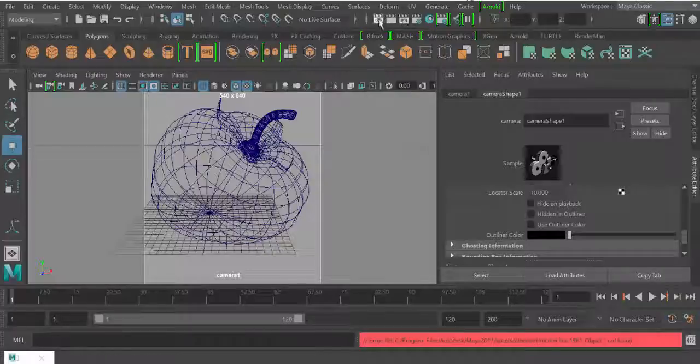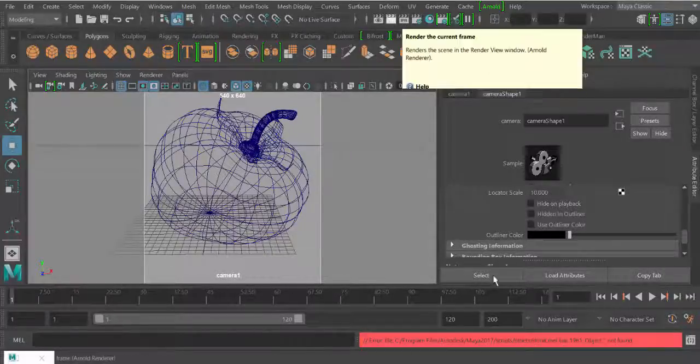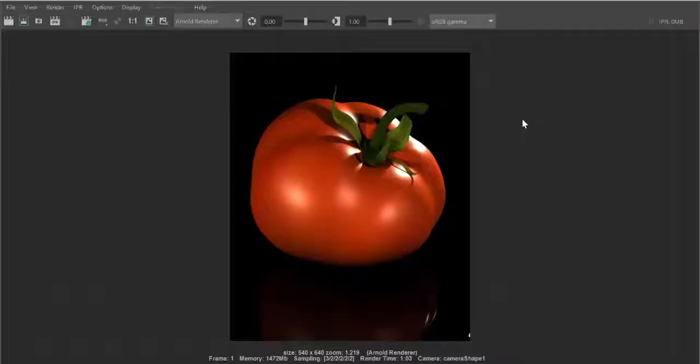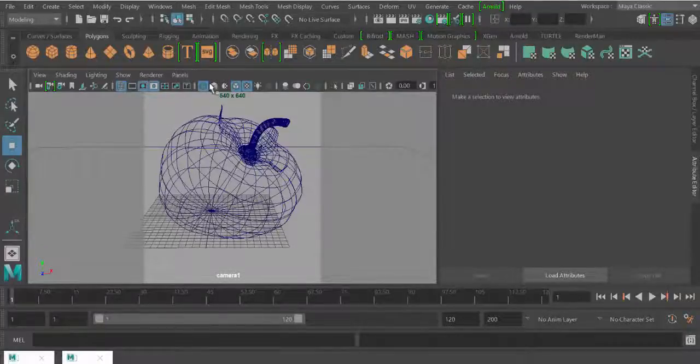Now I'm just going to take a quick render of this guy, so I'll pause the video. Alright, so this is my first render, and as you can see it took only a minute, but you can see this starting to look very nice. I can see a few things that stick out like a sore thumb. You can see that the shadow is just a little bit too crisp, and we can take care of that. And we also have these little dots around the place, which is basically anti-aliasing, so we can fix that with the render settings later on. So let's just minimize this and go back and see what we have.